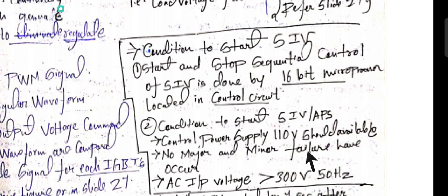Apart from that, 110 volt DC supply is specific for the train line signal. Then we have single phase 240 volt supply, which is located in the driver's cabin for charging the mobile phone, and also in the saloon area for the passengers. When passengers need to charge the phone, this single phase 240 volt socket supply is very important. So this auxiliary converter is responsible for generating these supplies: three phase supply, 110 volt DC supply, and 240 volt single phase supply.